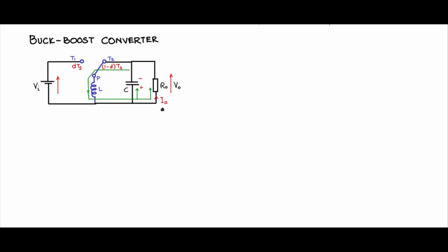So that is one difference that you would find in the buck boost converter with respect to the buck and the boost topology. This freewheeling action which causes the output voltage to develop is called the flyback action, and in the isolated version we call the buck boost converter, the isolated buck boost converter, the flyback converter. So anyway, let us now try to understand this buck boost converter with waveforms and try to find out what are the values of L and C and also the type of switches that you will use for the single pole double throw switch.